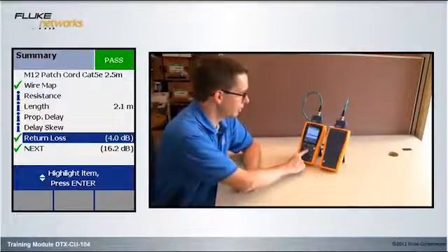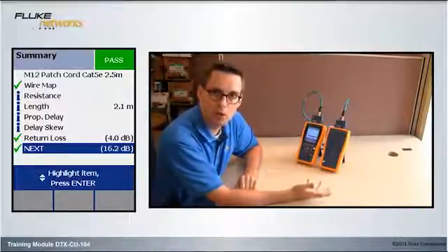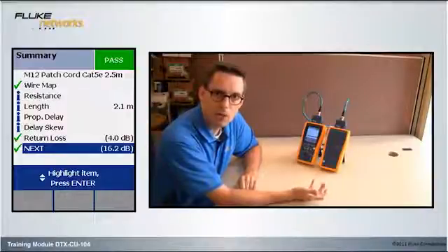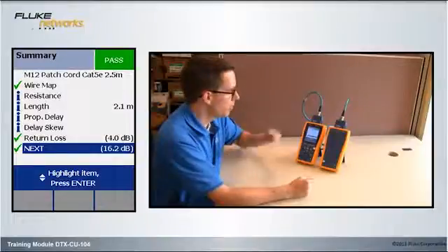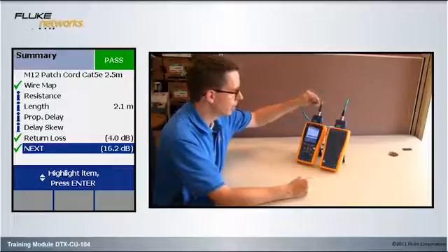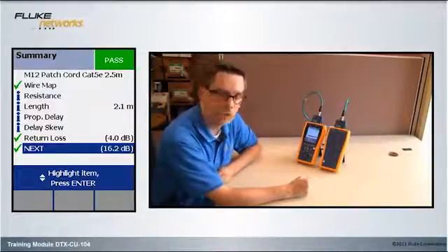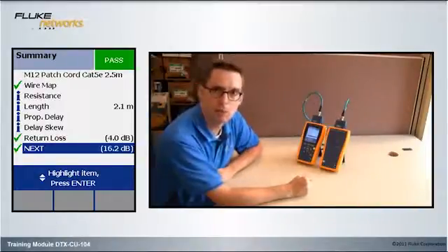And then we see near-end crosstalk showing 16.2 dB. Is that a good figure or a bad figure? Well, 6 dB is a factor of 2. So this is a really nice patch cord. Whoever did the termination of this M12 here and here clearly maintained the twists going into the back extremely well, coupled with a very nice performing cable, gives us excellent margin.